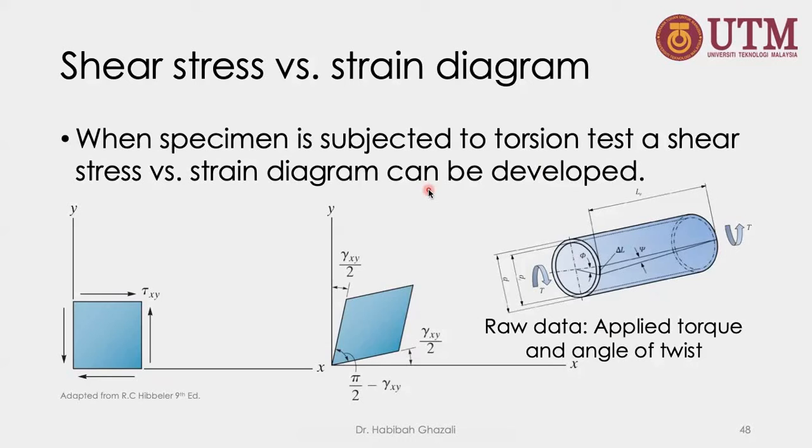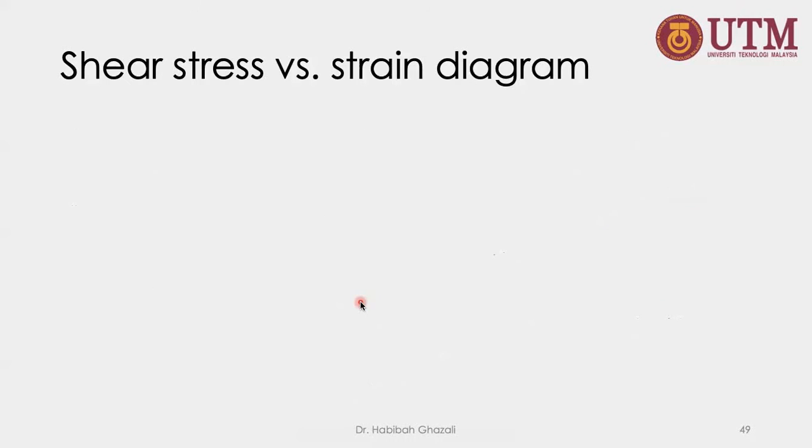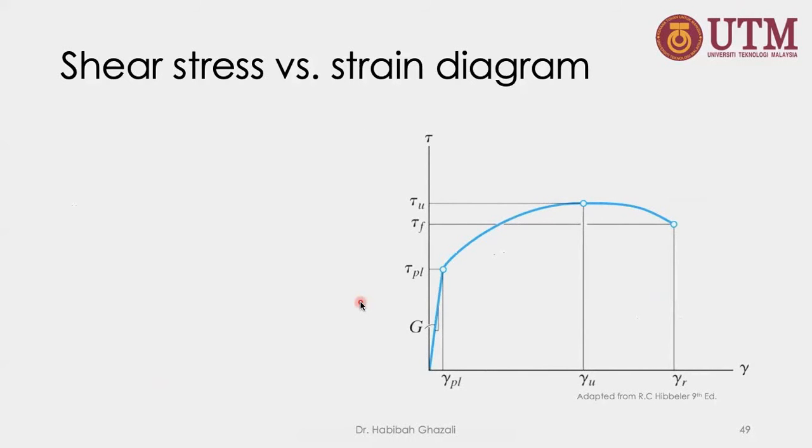So when you give a tensile load, each of the wires will experience torsion. So you need to know what the limit for the torsion is, whether the load that you give reaches a certain torsion limit, and whether it will turn into plastic deformation behavior. So how do they obtain this result? They also construct the curve by giving the load in the torsion direction.